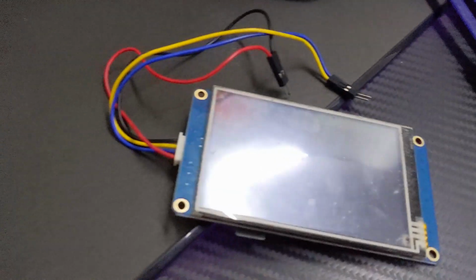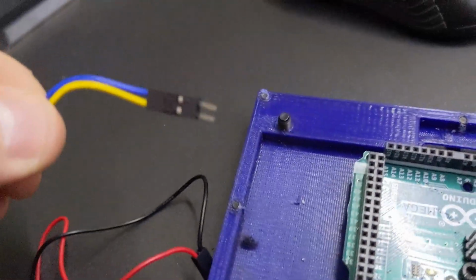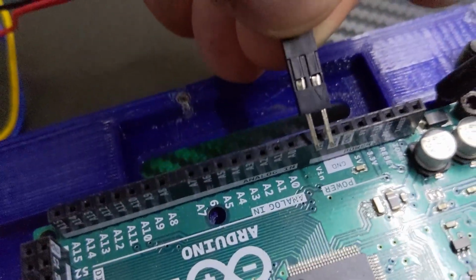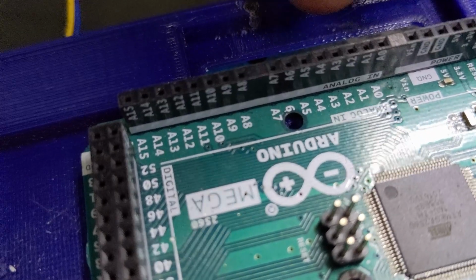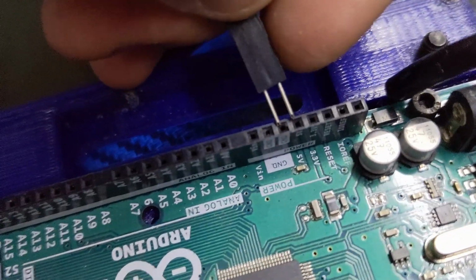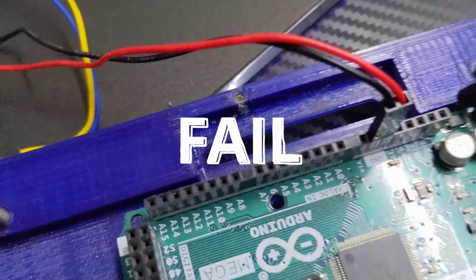So with the SD card in there, we'll hook it up to power from the Arduino. So for flashing, it technically doesn't need these communication wires plugged in. So we'll leave those out. Red goes into 5 volts. And black goes into ground. Like so.